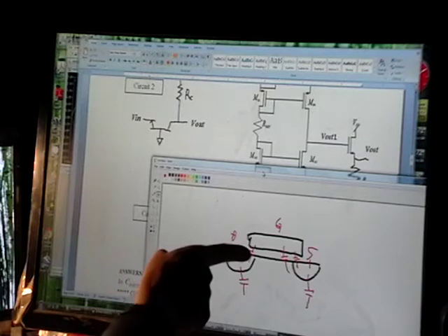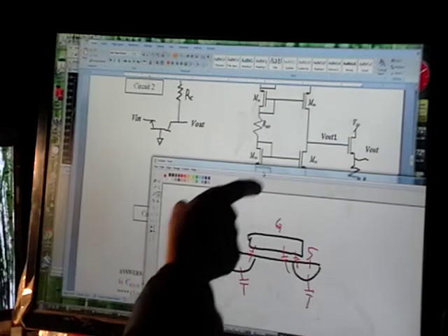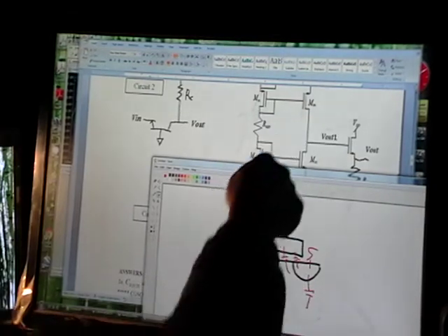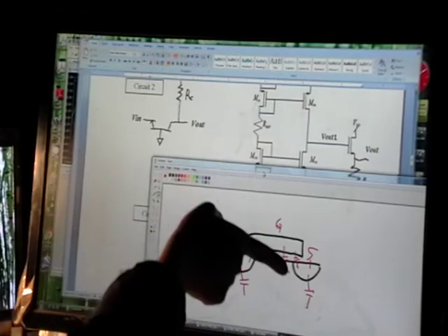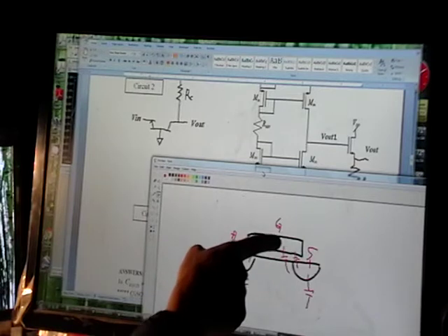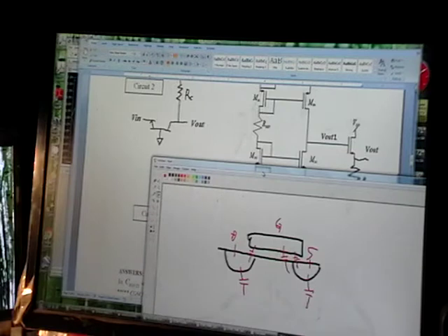You see gate drain overlap, you see drain bulk capacitance. Okay, so then you come out here and you hit the gate. So that means you're sitting up here. That means you see 1, 2, 3 capacitors. See gate drain overlap, see gate source overlap, and you see gate source. Remember, this is coupling to stuff in the channel, but just by convention they call that source capacitance.